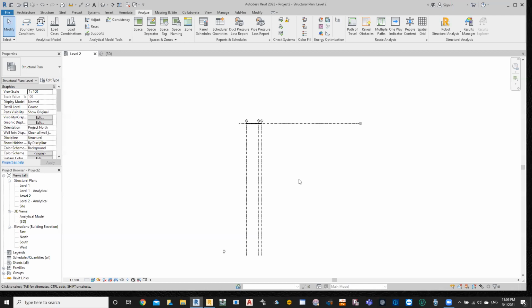Now the next session, I don't want to push a lot of things. The next session is going to be dealing with Robot. We are going to do the initial setting in Robot, and we are going to change the cross sections of the beams and the slabs. I'll teach you how to do that according to the dimension. Now for the beam, you can get the dimensions easily, and then you can change them. For the slab, you need to know each slab's shorter direction, and accordingly you will give the depth as whatever I have given you in the first session.